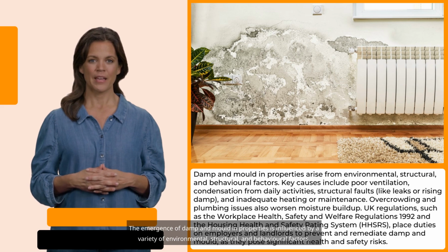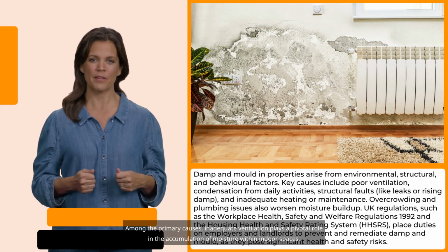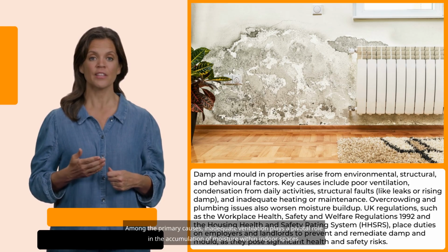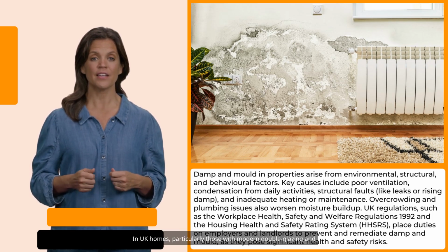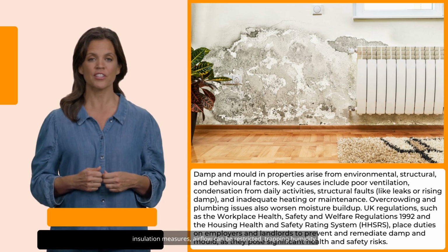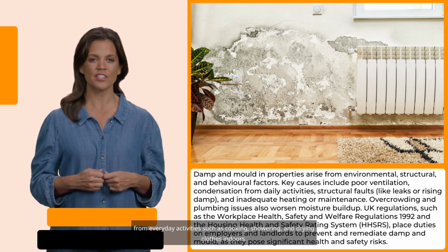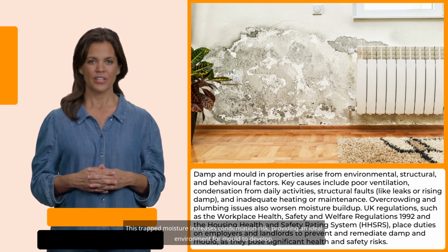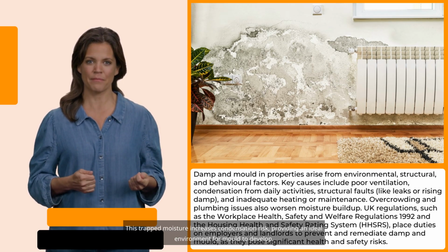The emergence of damp and mould in properties is influenced by a variety of environmental, structural, and behavioral factors. Among the primary causes, inadequate ventilation plays a pivotal role in the accumulation of moisture within indoor spaces. In UK homes, particularly those with modern double glazing and insulation measures, airflow can be restricted, trapping humidity from everyday activities such as cooking, showering, and drying clothes indoors. This trapped moisture increases condensation risk, providing an ideal environment for mould to develop.